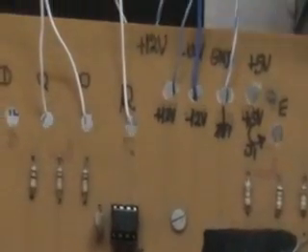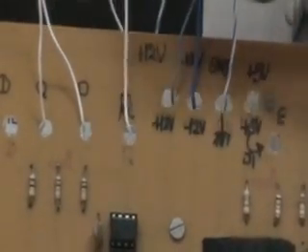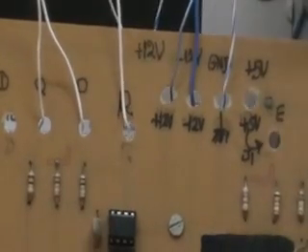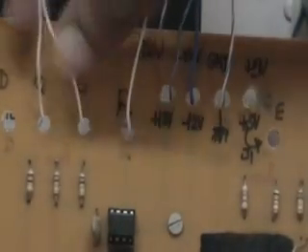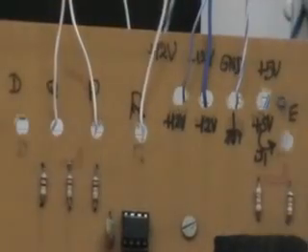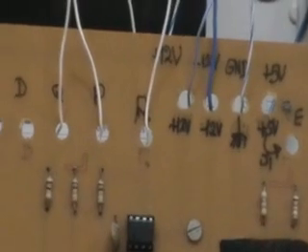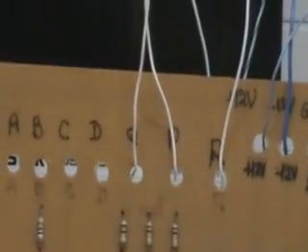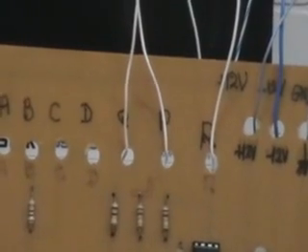If you give two inputs to Q and P, the outputs will be the difference of voltages across Q and P. So it is given in the manual that VR is equal to VQ minus VP. So you should not forget connecting the plus 12 volts, minus 12 volts and ground connections in the PCB.